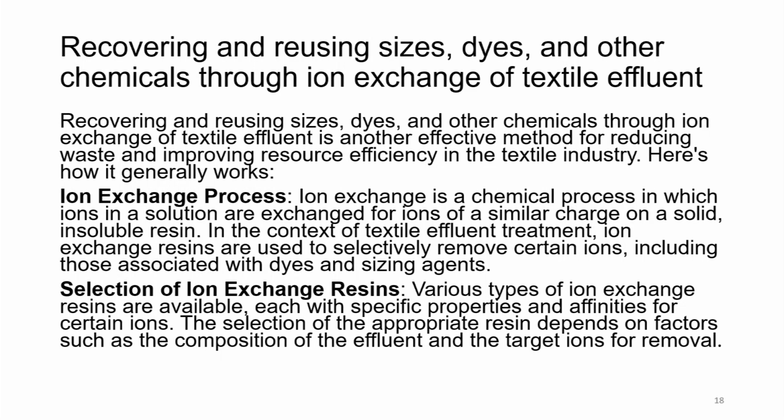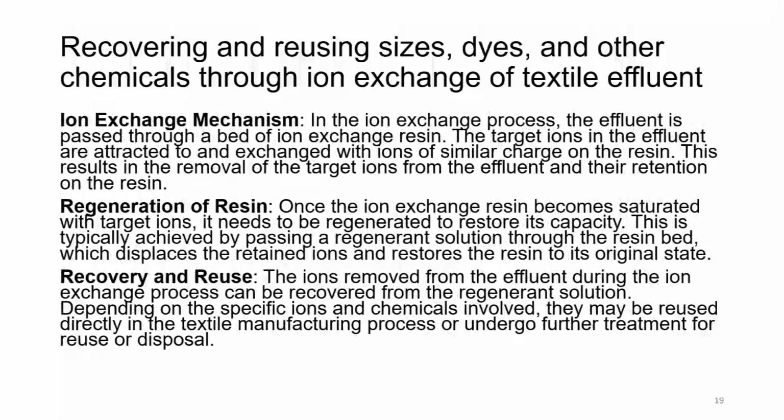Selection of ion exchange resins. Various types of ion exchange resins are available, each with specific properties and affinities for certain ions. The selection of an appropriate resin depends on factors such as composition of the effluent and the target ion for removal. Now, this is crucial. Which ion we want to remove and how much of it is present in the textile effluent. So, based on that, the ion exchange resins are chosen or selected.